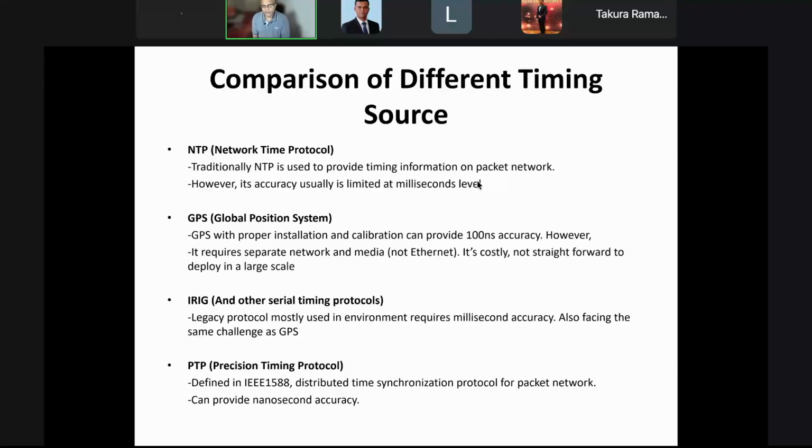We were using Network Time Protocol for many decades. Now it's based on the time requirement and the goal. We should consider Precision Time Protocol and its implementation based on the IEEE 1588 standard. There are three variants so far: version 1, version 2, and version 3, which is very recent and not ready for real-world deployment.